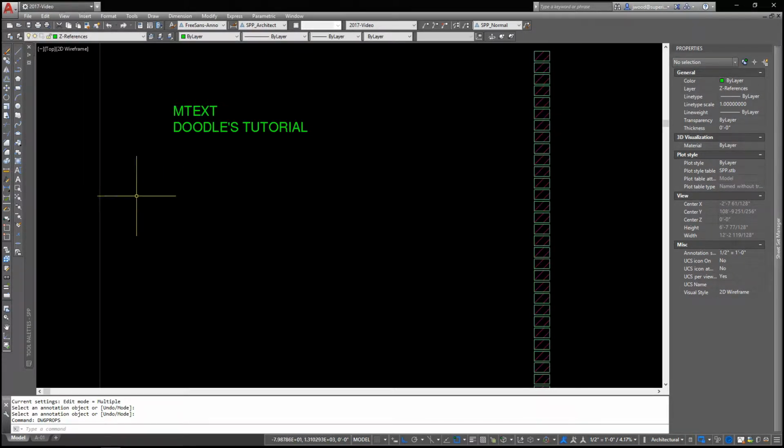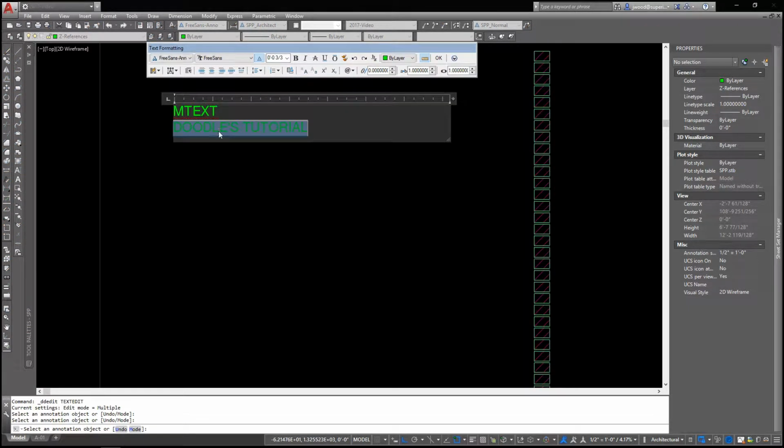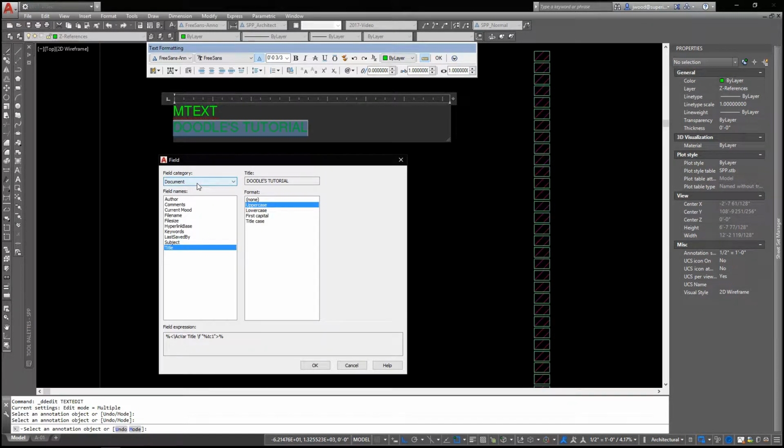But if I don't think about that, I am feeling peachy keen, so that's what I'm going to set that property to. A custom property of my own. If I go back and edit my mtext, let's edit that field, I don't even have to go back to all because it's actually a document property. You'll see that there is current mood right here and peachy keen.